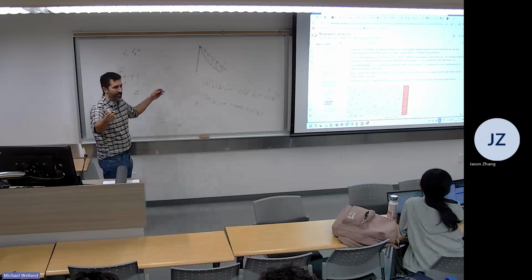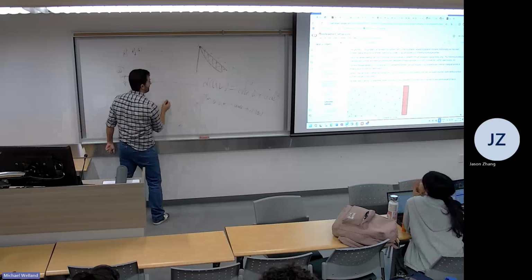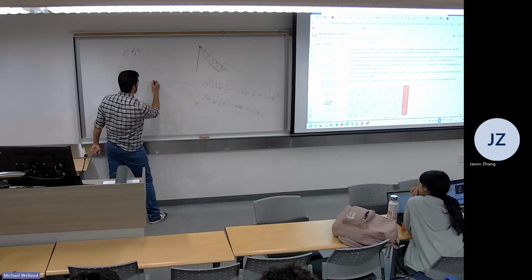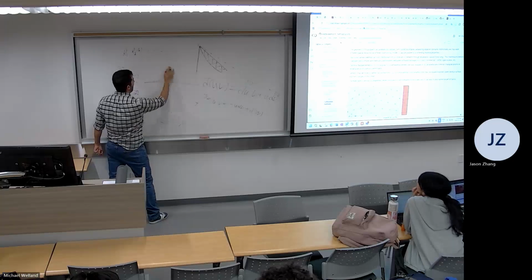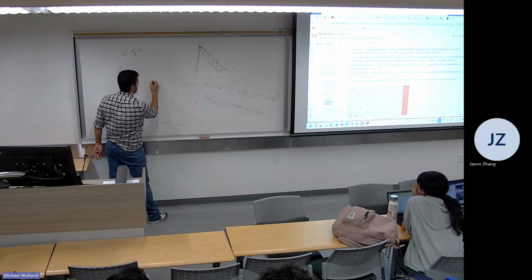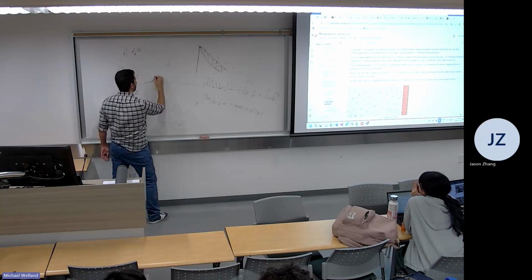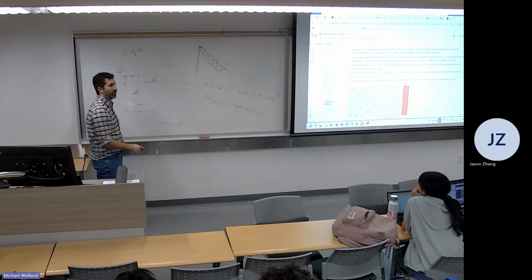Boundary layers, and this is also to do with assignment 7, right? If you have a no-slip condition here, your velocity field is 0. Up here, your velocity is something in between. You generally have a pretty fast resolved gradient, hint, hint, right? Followed by some kind of tapering off.